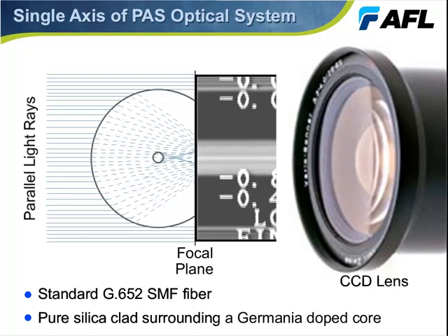So at the very top of the fiber and the very bottom, the image is completely black because all of the light rays from the LED have bent inwards. So the light is focused in at the center, and due to the secondary bending of the light at the core cladding interface, there is a very bright streak down the center of the bright region. And that is what tells us the position of the core relative to the cladding.